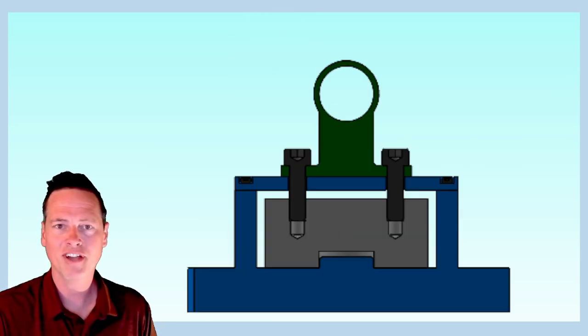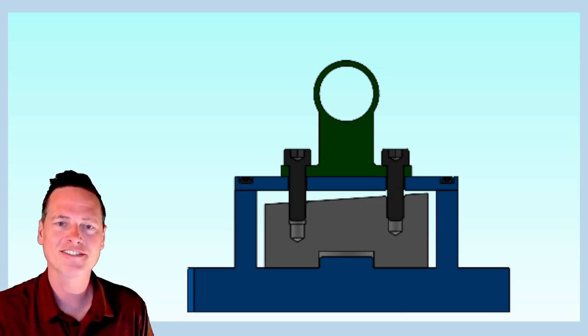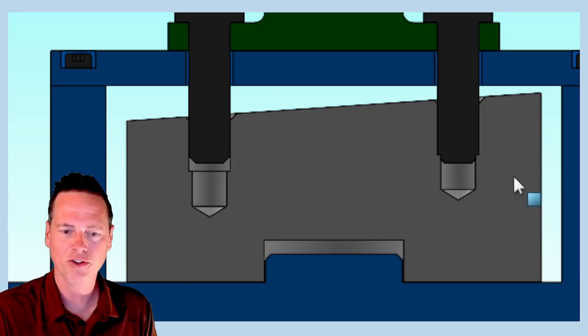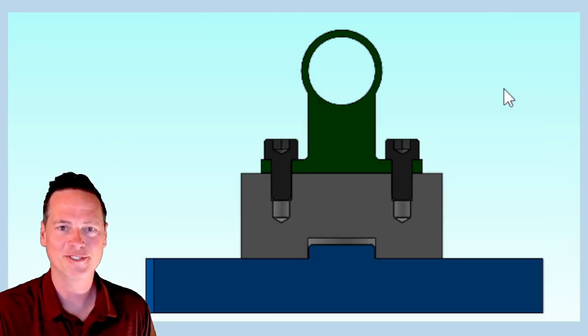This way, even if the top surface of the gray part was slanted like this, within the size tolerance, the threaded holes would still be controlled as normal to the bottom surface. But that would be a pretty uncommon way to use the threaded holes on our gray part, wouldn't it? We want this far more common usage here, right?